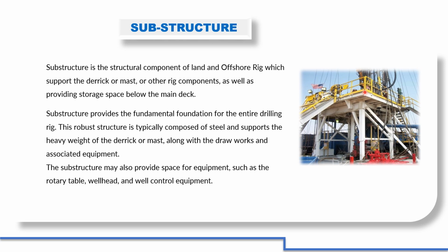For example, the draw works, the rotary table, the winch, the driller's cabin, the doghouse and the iron roughneck. So it's a very important structure and part of any drilling rig. The substructure is very important. The substructure is the structural component of land and offshore rigs which supports the derrick or mast or other rig components, as well as providing storage space below the main deck.